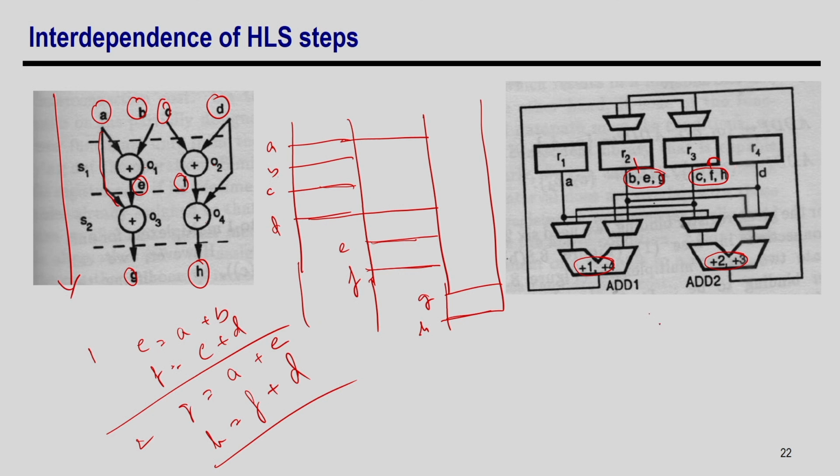You can do this as homework and identify these interconnections, and you can see here a total of 6 muxes is needed, right. These are all 2-bit muxes, and a total of 6 control signals is needed because all are single 2:1 muxes. So, this is one possible mapping.